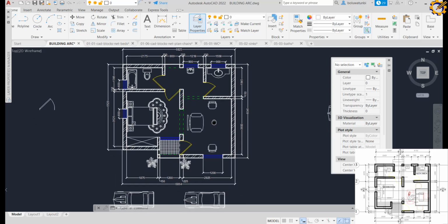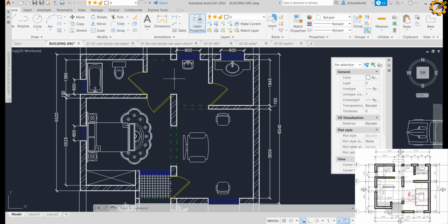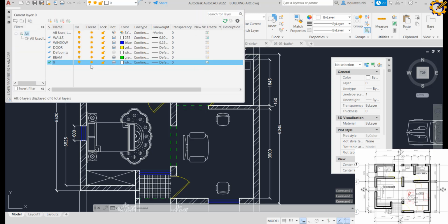It shows some of the features and the likes. Imagine I want to apply some tiles. This is my kitchen, so let me apply some tiles to this kitchen now. To apply tiles on this kitchen, I need to hide this. Which means I need to create a layer for my items. So let me create a layer for sanitary items.